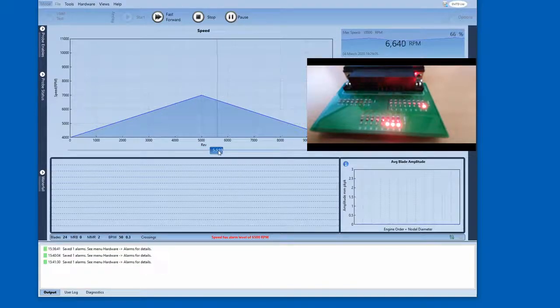If I go down the other side, you can see at 6.5, we go from error to warning. There we go. Error code still on, alarm still active. So if either the warning or the error bit is high, you're in an alarm condition, or you're in a warning condition, and the code will always be present during that. But as the speed goes below 6,000, you'll come out of warning and the alarm will go away. There you go.